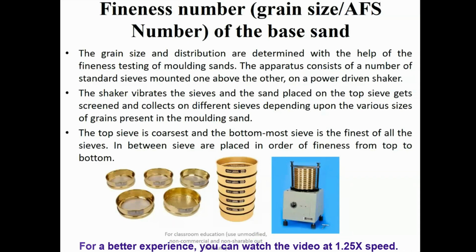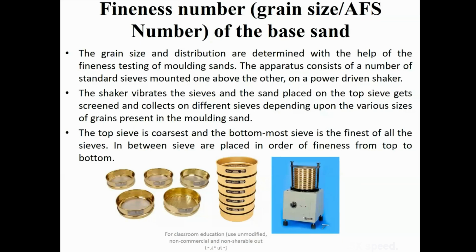The fineness or the grain size of your sand sample is a very important parameter because it influences the strength of your mold and also controls the permeability of your mold. This grain size and its distribution are determined with the help of fineness testing of the molding sand.